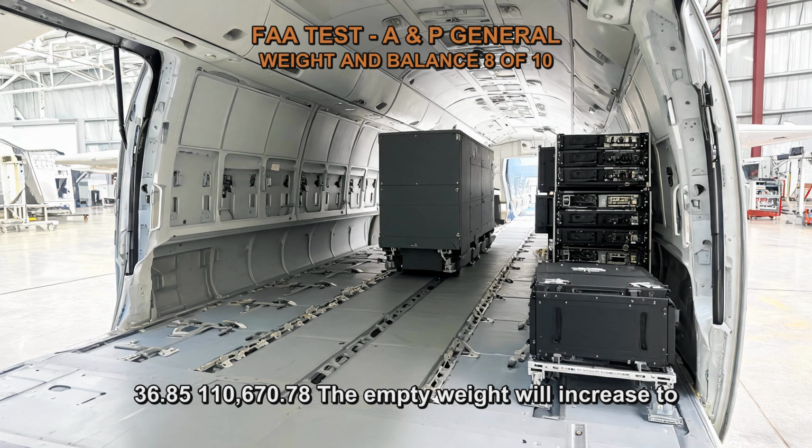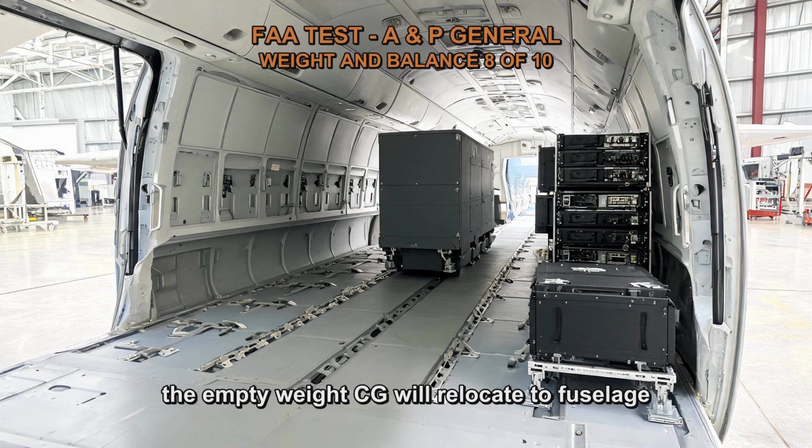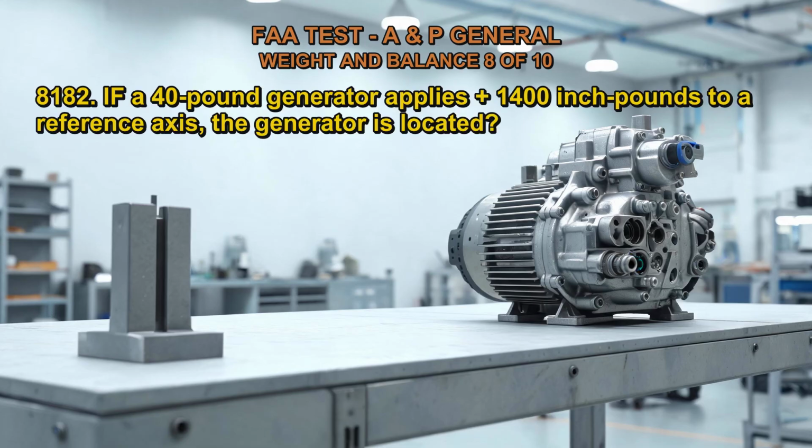110,670.78. The empty weight will increase to 3,003 pounds with the modifications detailed below, and the empty weight CG will relocate to fuselage station 36.85. The empty weight CG was at plus 35.23 prior to the alterations. The new empty weight CG is 1.62 inches behind the old at plus 36.85.